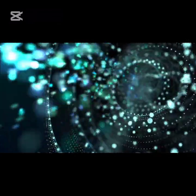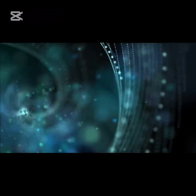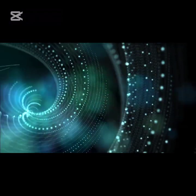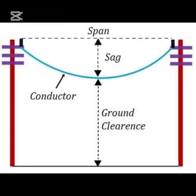Now that we know the benefits of sagging, let us explore the disadvantages of excess sag in power lines. Having too much or loose sag in power lines can lead to several drawbacks. 1. Decreased ground clearance. Excess sag can lower the vertical clearance between conductors and the ground or structures, heightening the risk of electrical arcing, fires, and safety hazards.